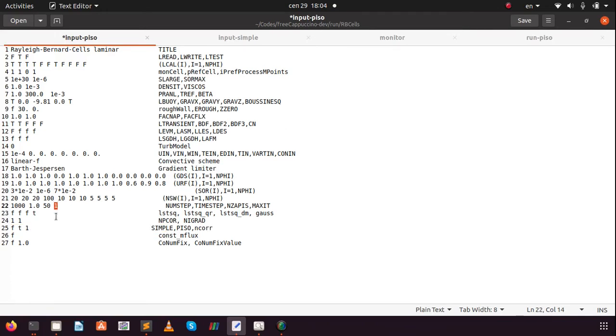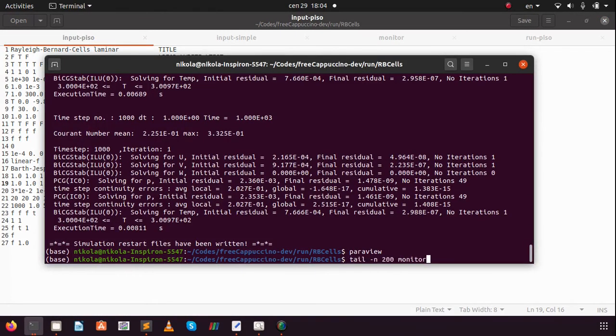And just for this time, I want to show you, we will set number of outer corrections to 2. And here, where we set under relaxation factors, we will say 0.8 for pressure. Let's have some under relaxation for pressure field, and let's repeat once we solve everything. Let's go back once again and once again solve momentum predictor and then pressure. Everything else is the same.